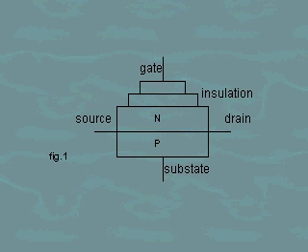The topic for this lesson is metal oxide semiconductor field effect transistors, MOSFETs. Metal oxide semiconductor FETs, or MOSFETs, do not have an actual p-n junction. When a metal oxide is not used to insulate the gate in the device, it is known as an IGFET, insulated gate field effect transistor. However, the gate is insulated from the channel source to drain current path in both types.